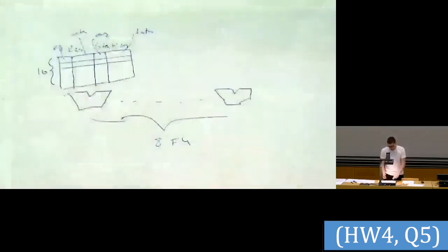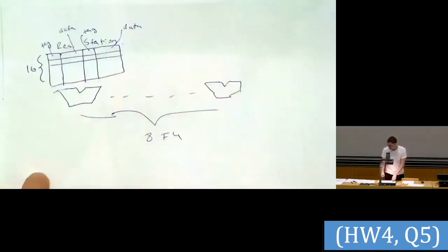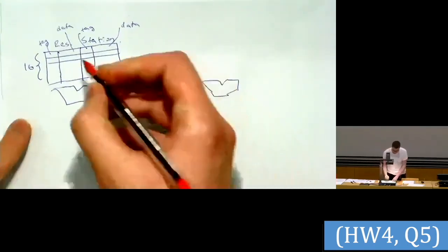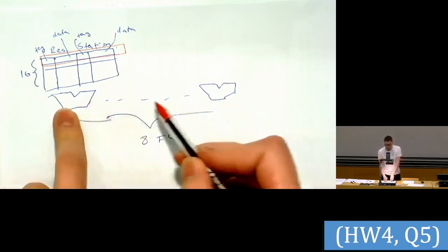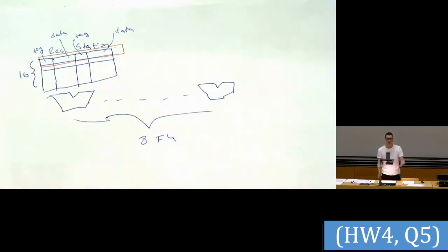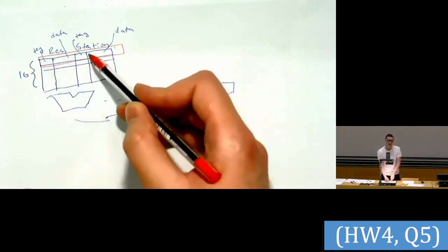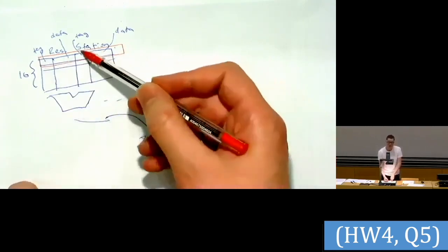So if we go back here, in a single reservation station entry we have two tags, because we have 2 source operands. And we will need a comparator for each tag for each functional unit, because in the same cycle, each of those 8 functional units can produce a result, and this result needs to be compared with each of the tags in the reservation station entry.